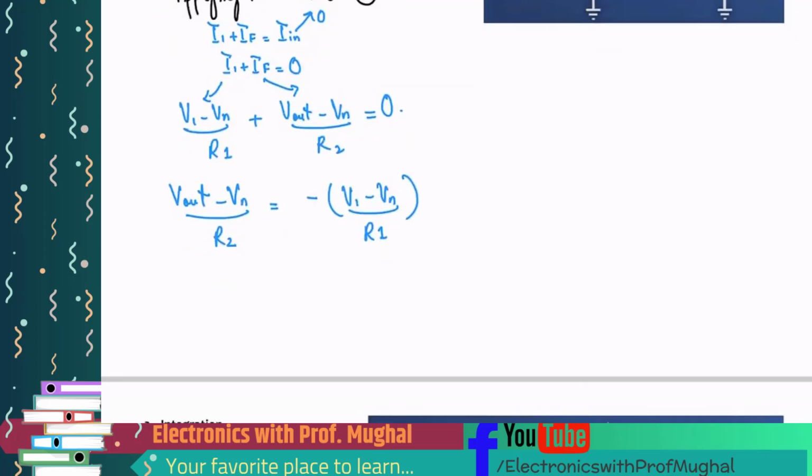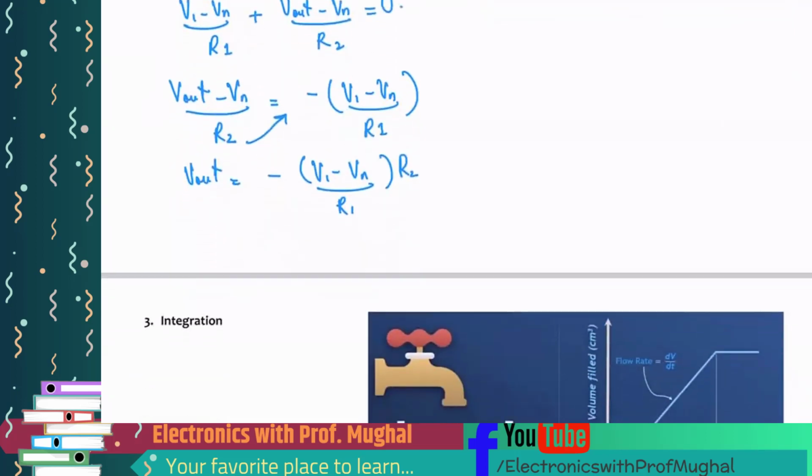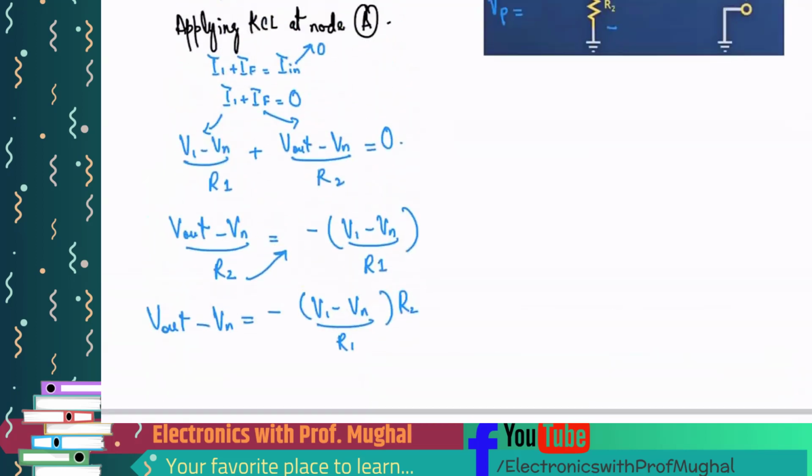If I multiply by R2 and take it over there, then I get Vout equals negative V1 minus Vn over R1 times R2, correct? And then from here, on this part right here, I have Vout minus Vn equals to, yeah. And then from here, maybe I'll just go here.